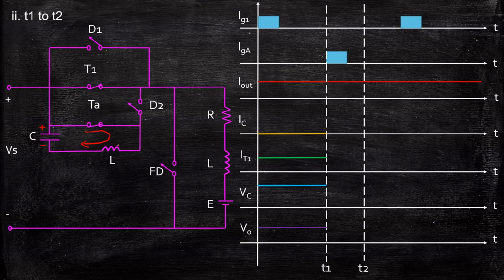So the energy in the capacitor will start going into the inductor with a polarity plus and minus. The inductor will start charging. Again, the capacitor energy will go to the inductor and the inductor will reverse its polarity. Again, the capacitor keeps charging. This process I will explain, but in general, this is basically an LC tank circuit, which is an oscillatory circuit. It keeps charging between the capacitor and the inductor over here.